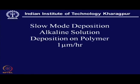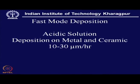Now, we have two types of deposition. One is called slow mode deposition. Here the growth rate is about 1 micron per hour, and this is an alkaline solution, and this alkaline solution is good for coating on polymer. But when it is a metal or ceramic surface, we can go for a faster rate, and then the solution is acidic in nature, and 20 to 30 microns per hour is not a very difficult task.